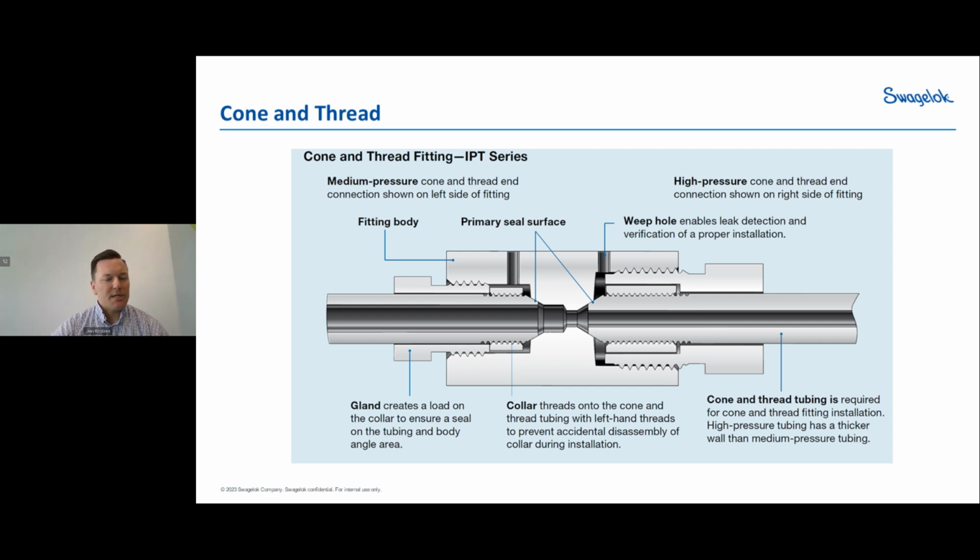But it also allows an ingress path for environmental factors that could potentially cause corrosion of the base fitting material. High pressure applications, particularly offshore and in marine environments, could be susceptible to that type of corrosion because there is that entrapment area.